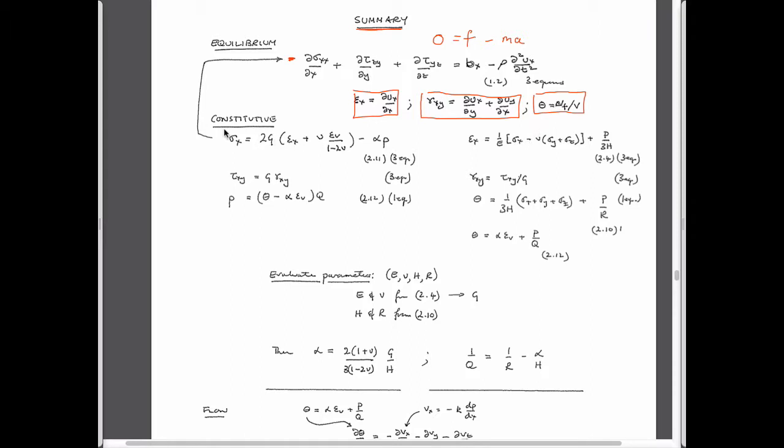We have constitutive relationships. We have the ones that we talked about in terms of Hooke's law, written in the usual forward way, strains being related to stresses, but also with fluid pressures added in. Fluid pressures, through the effective stress law, don't act on the shear behavior.